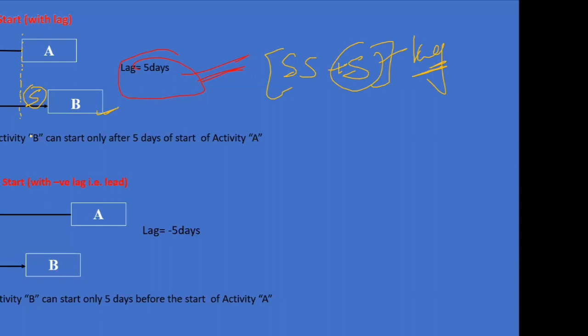Now take a real case scenario where you can do this. Let's suppose at the very initial stage you have 16 footings. To do the PCC work, you will definitely not wait to finish the excavation in all 16 and then start the PCC. This is not how it works in actual.